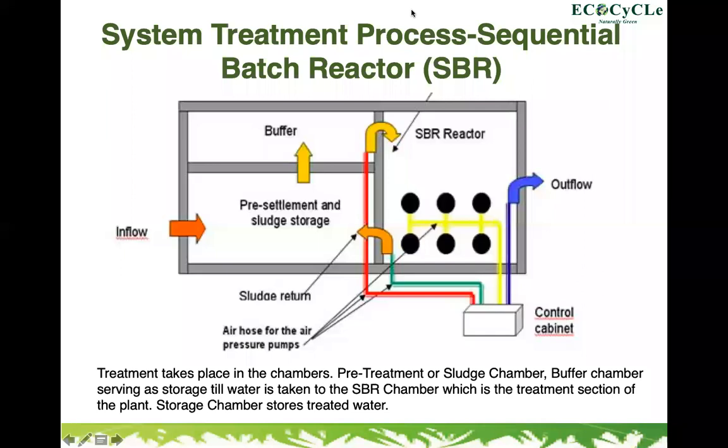Okay, Lucy? Yeah, in case we have high temperatures, the only issue that would be affected is our electrical cabinet, and the reason we have the MCBs and contactors, the protection, is so that if there is any issue with high temperatures, the thermal trippers will check in and trip and prevent our motor from burning out. So that's why we have the requisite protection.